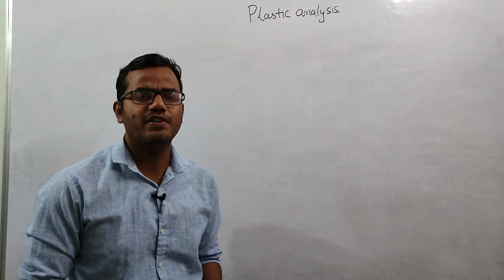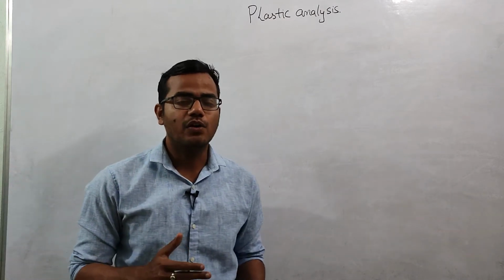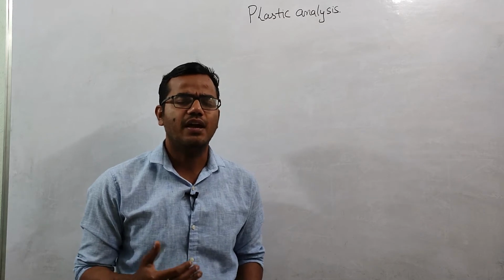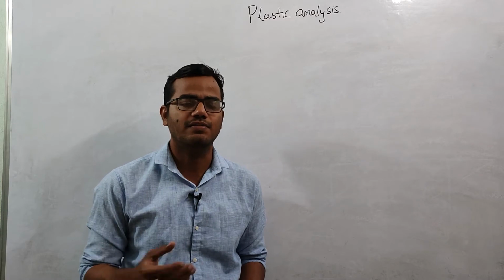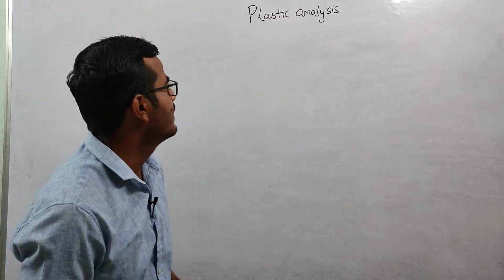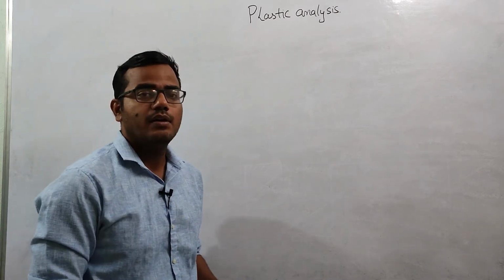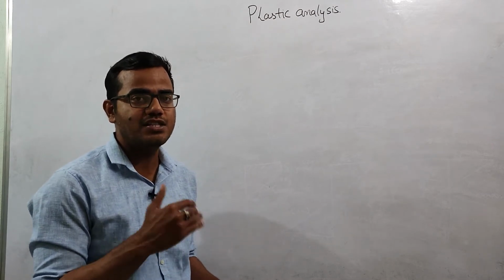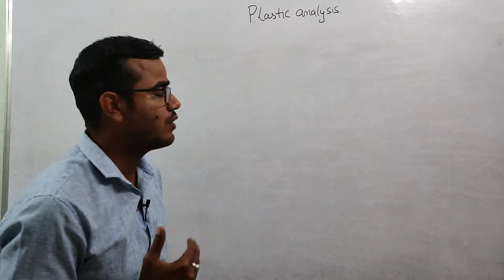In the last lecture, we discussed the plastic analysis theory, and also what the advantages are if we design our structure as per the plastic analysis theory over the elastic theory. We made some conclusions there. We also discussed that in plastic analysis, each fiber in each cross section will yield, and it will give a moment which we call the plastic moment.